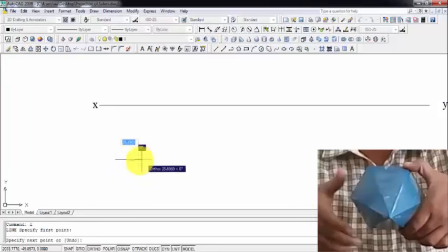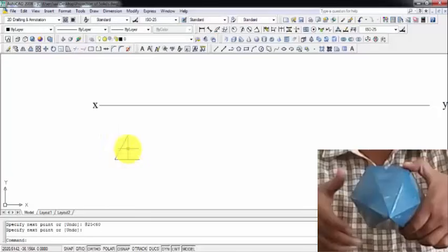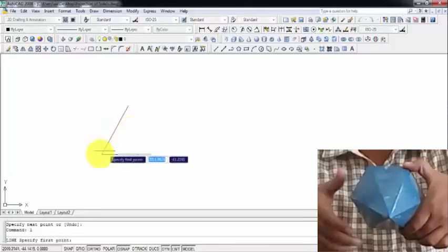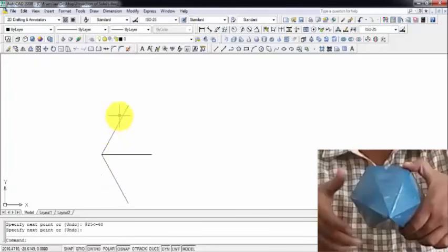And let me make a small reference line with respect to which I'm going to go 25 millimeters. Okay, and this is going to be 60 degrees. Now please watch this carefully. The same step has to be done down below. This is again going to be 25 millimeters, again at an angle of 60 degrees, but in the clockwise sense. A hexagonal geometrical shape has internal angles of 120 degrees. So 60 above and 60 below, this total is going to be 120 degrees.